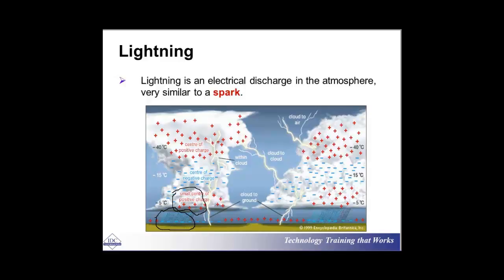That's why you just walk freely, and we have a lot of cables, a lot of transmission lines or something. You just walk, you just drive, and you are safe. Nothing happens because you have air. And that air has dielectric strength, and that air prevents that live conductor from damaging, injuring, or killing you. That's what it is. But if you get very, very close to bus bars, to live compartments, to transformer bushings, to, I don't know, panels or something, yes, you could be electrocuted because that dielectric strength is compromised. This is what is happening in here.